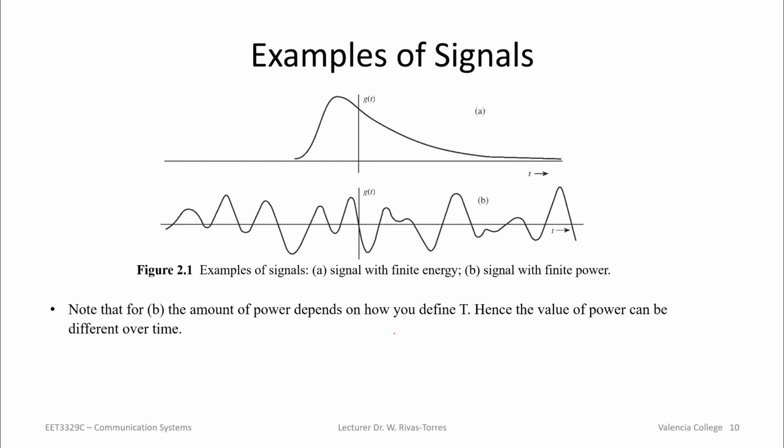Here are two examples. So the first signal, notice that after it goes through a certain peak, you can see the signal diminishes, diminishes, and continues to diminish to a point that if we let time continue to run after this point here, you would see that the signal eventually will reach zero. So think of this as some kind of circuit. There was some capacitor or something. Initially, you got a charge, you remove the DC source or whatever source, and it begins to discharge. And eventually, it will go to zero unless you apply more energy to it.